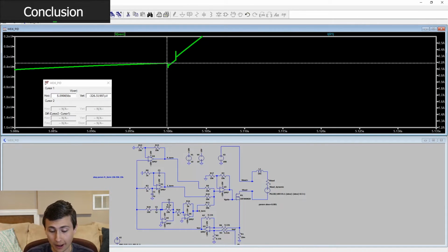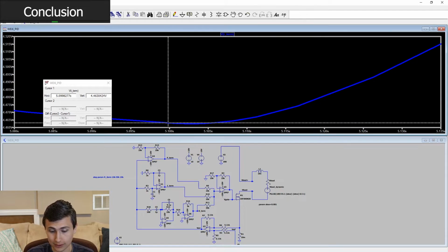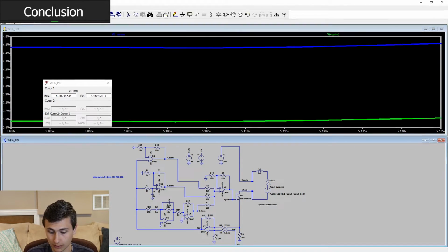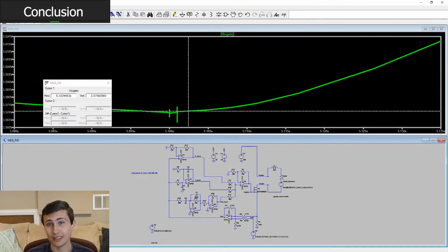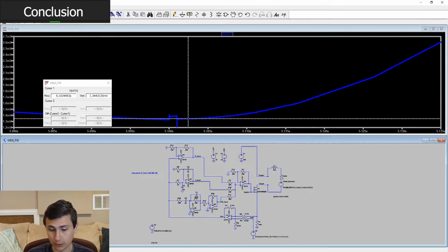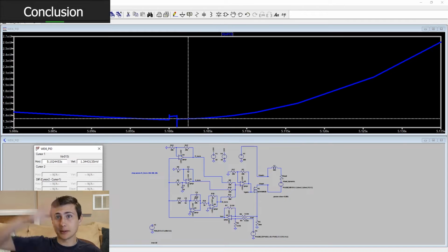Still didn't quite get there. However, thankfully, it's because our I term is still cruising. Our I term is still getting lower. The gate voltage is still going down. It's just hard to drive something designed for 25 amps down to such a low current. It's almost as if someone desiring to have high precision at low currents could have multiple stages, where you might have one FET designed to go from maybe 0 to 5 amps for that high degree of precision. Then you have your high power FET designed to carry it from 5 amps up to 100.